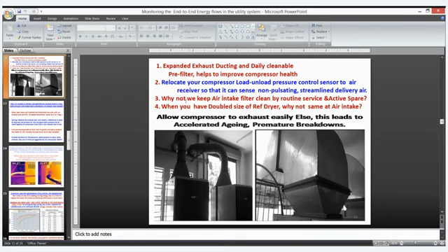That is one zero cost monitoring. Daily we monitor, and we will have an active spare filter as a pre-filter replacement, and we can routinely clean and keep the filter ready and maintain the Pascal drop across the air intake filter at less than 500 or 1000 Pascals instead of 2000 or 3000 Pascals. There itself, we can definitely have a flow increase from the given compressor. It's a low cost monitoring, low cost proposal and low cost measure, immediately implementable on day one once you go back to your industry.